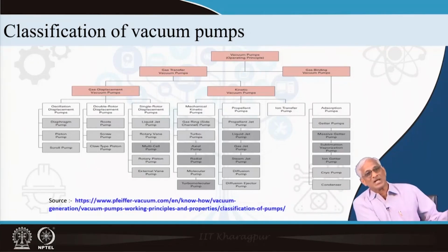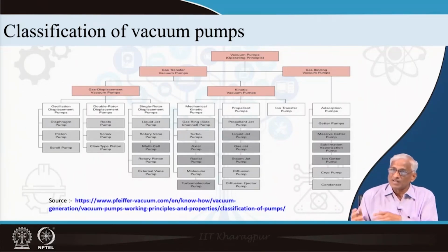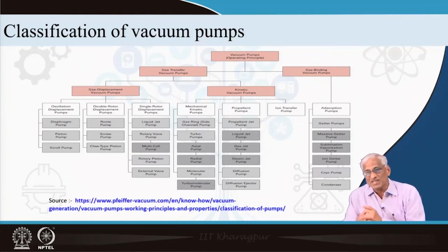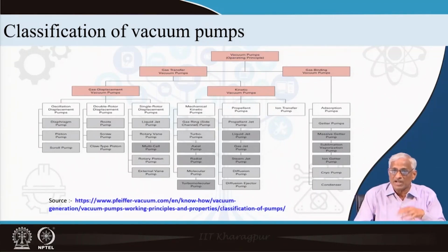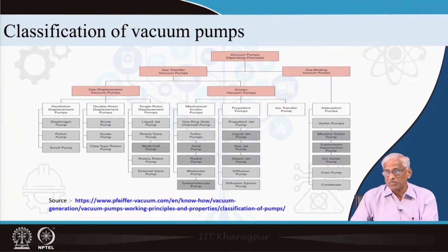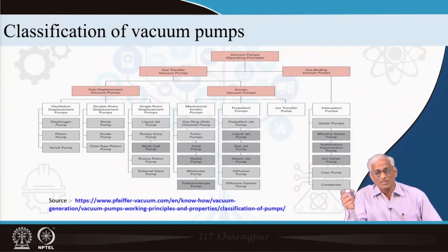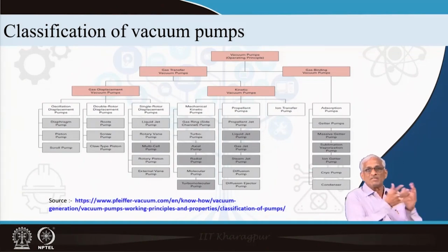So, vacuum technology has used other developing technologies like turbines and trying to make pumps out of it. Vacuum technology has also used cryogenic engineering and tried to make cryogenic pumps. Vacuum technology has also used steam jets etc. to make steam jet ejectors. Vacuum technology has used IC engine concepts or many other things like valving and compression, expansion. It has produced certain pumps like rotary piston, rotary in a rotating thing or a linear motion, rotary motion. Varieties of processes have gone into that, meant for various pumps. So, like every other technology, you have a variety of pumps based on variety of physical concepts.